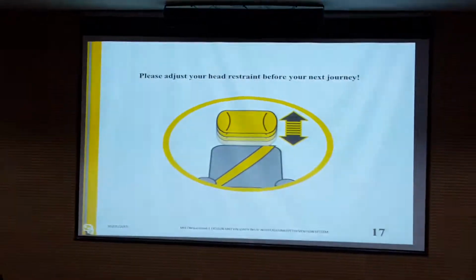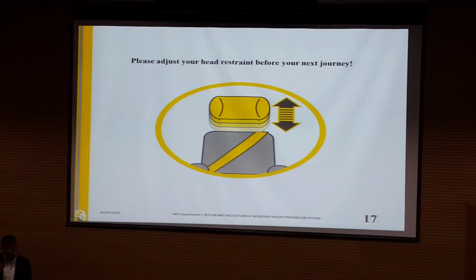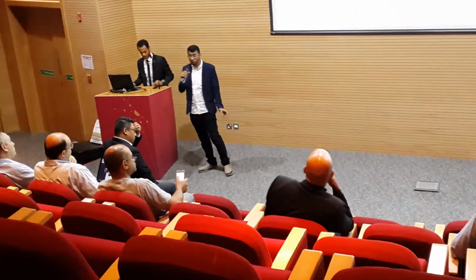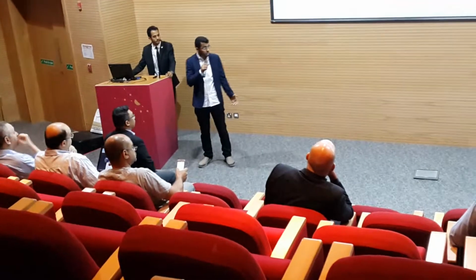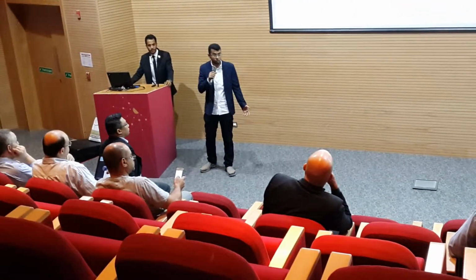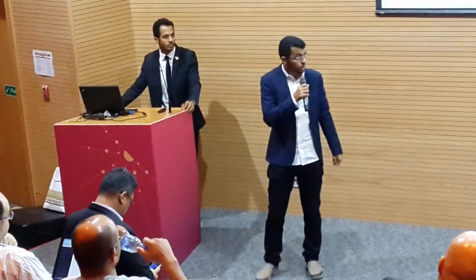So working on this project, we have learned many things. One of them is that mechanical engineering is not only limited to machines. We can deal with the human body through the gate of biomechanics. Also, we figured out the importance of simulation solutions since the researchers couldn't reach their results using a real human body due to some limitations. Finally, I would like to advise myself and you to adjust your head restraint where the correct position is when the head restraint comes to the center of the human head, and try to keep the backrest distance as small as you can during driving. And thank you.